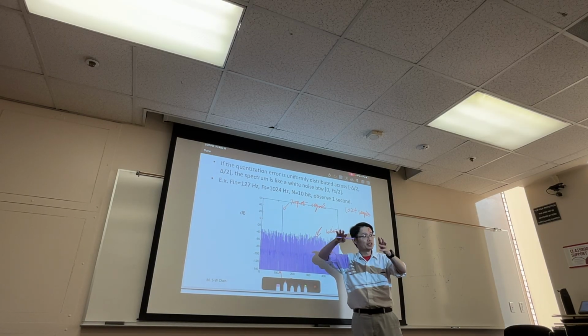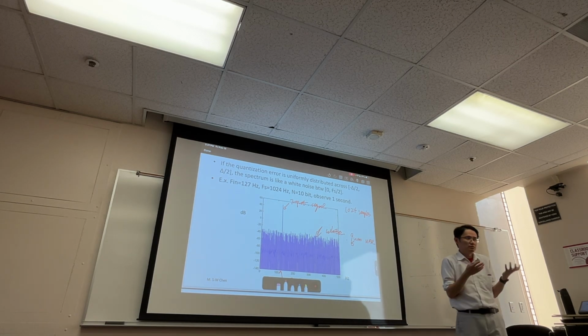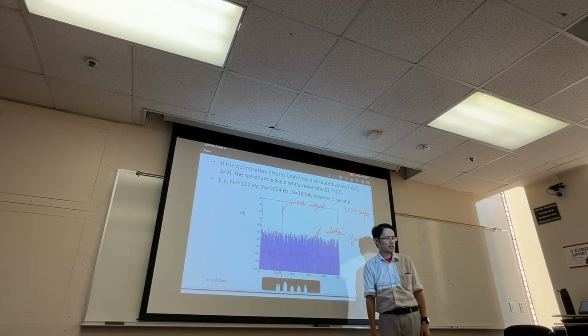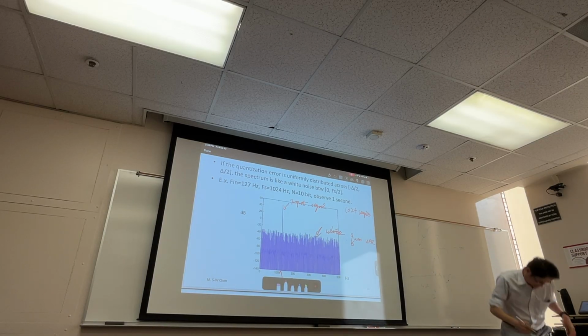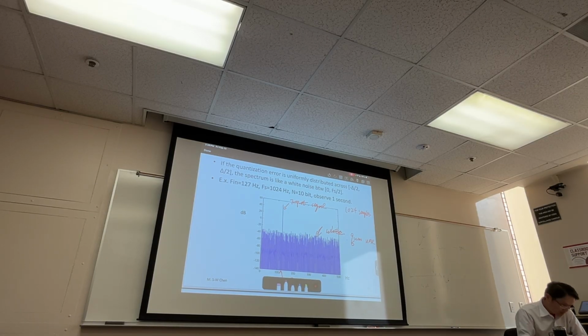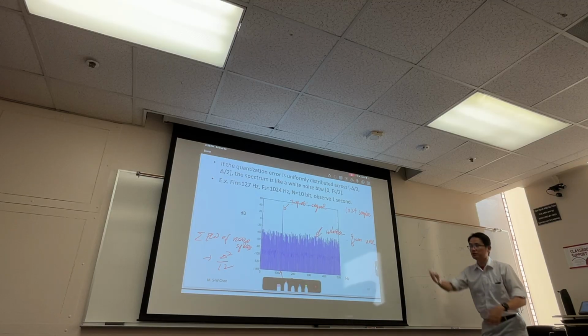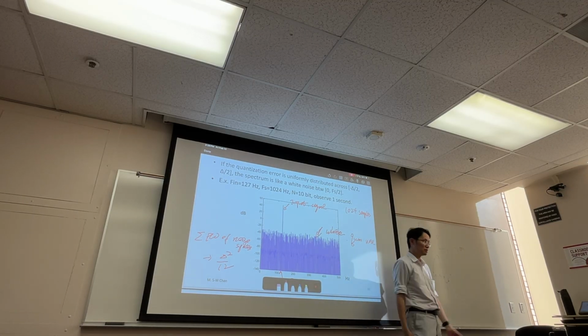So you have another 1023 spikes. Sometimes people call them beats. So you sum up all this power, what do I get? One. The step size squared over 12. What is that magic equation? I suggest you remember it. Of course, you have to look at the normalized delta, right? So you normalize that, then you get this power. So that's exactly it.